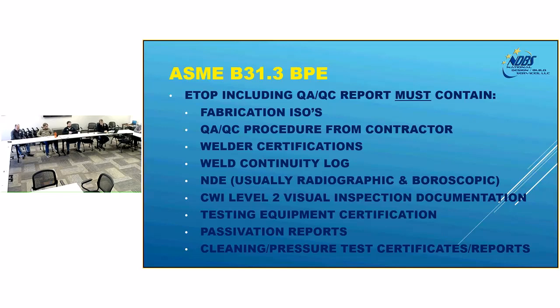Any system that conveys product, if we get into stainless steel tubing that is conveying, like in the food and beverage industry, we're doing this Arizona tea. Had we gotten into the product conveyance of the sugars and the sucroses, those systems have to be passivated. Or if we would have gotten into the clean in place systems, there's a lot of distribution piping for the clean in place, CIP, those systems have to be passivated.